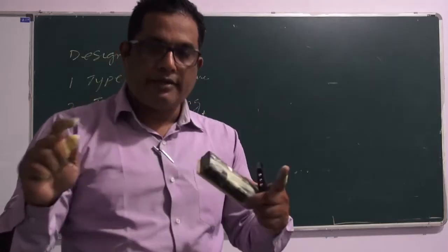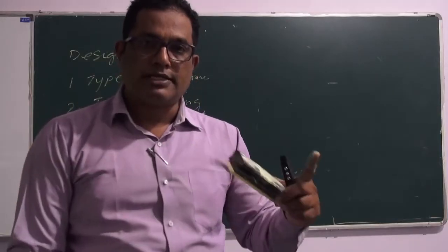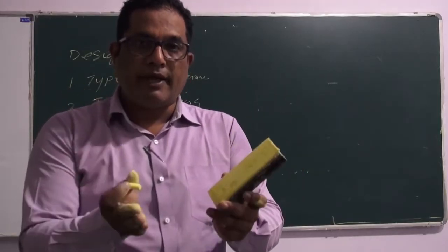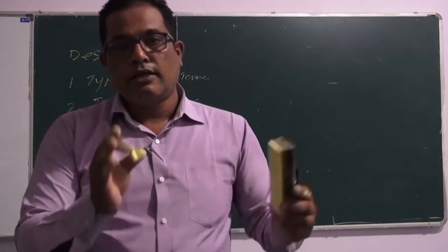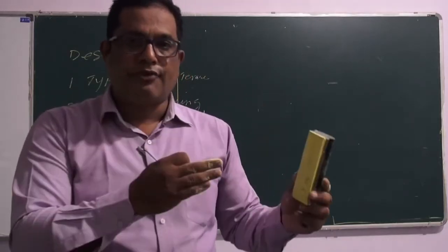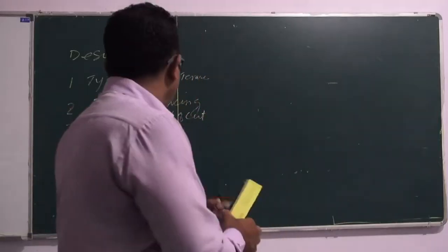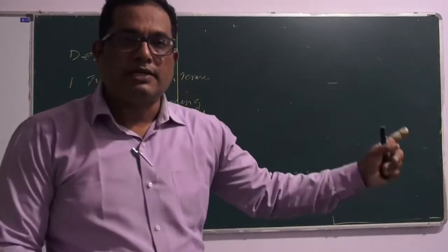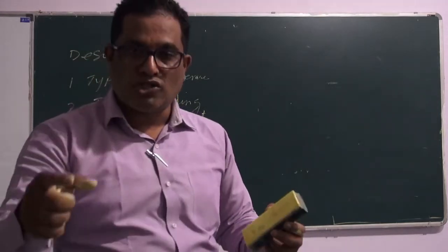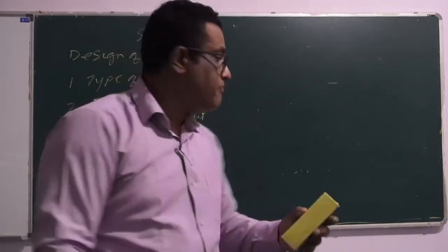Normally a 1:8 grade is given on the terrace bed. And also the channel bed has to be designed. Should it be parabolic? Should it be trapezoidal? That channel bed has to be designed. We won't go this far, but we'll limit ourselves to the terrace spacing and terrace width, and also the area lost due to bench terraces.